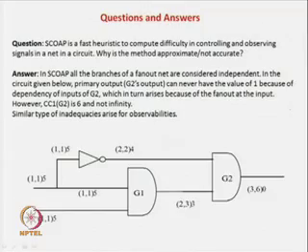Now, you can set up a threshold, so that whatever is lower than that threshold will be an easier to test fault, and whatever are difficult to test faults will be higher than the threshold. Based on this demarcation, you can easily find out which are the easy to test faults and difficult to test faults. For the easier ones you will apply random patterns, and for the difficult ones you can apply the sensitize, propagate and justify approach. But it is a heuristic.